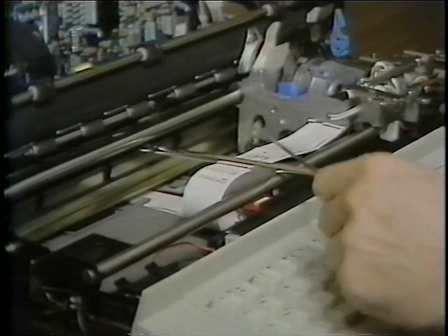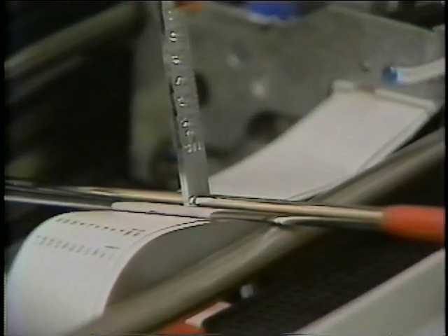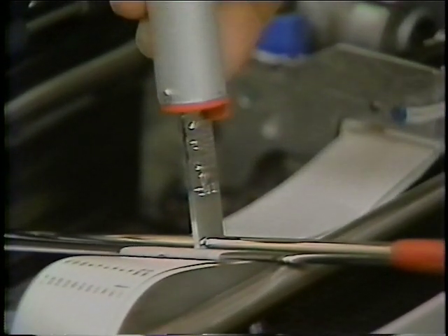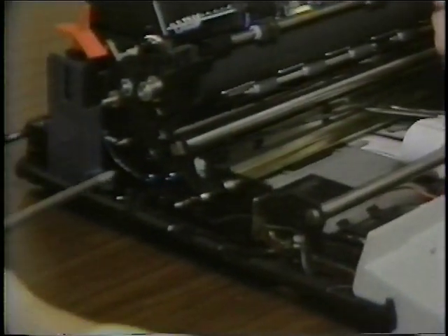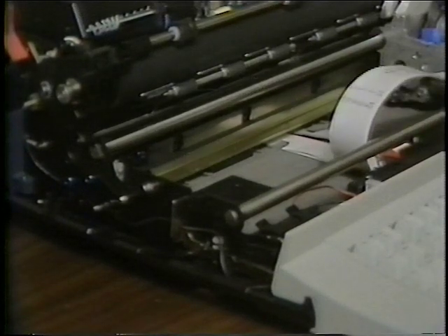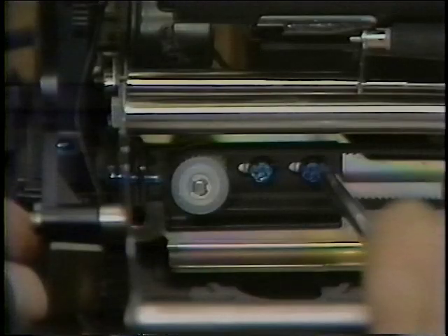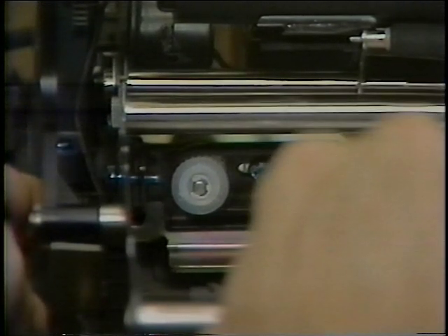Then slide the T-bender over the top of the transport belt at its center and rest the T-bender on the front shaft as shown. Place the spring scale on the T-bender 30 millimeters from the center of the front shaft. Apply 5 3/4 to 6 1/4 pounds of pressure on the T-bender at a 90-degree angle. Then turn the adjusting screw in or out so the bottom of the T-bender just touches the bottom transport belt. Finally, tighten the idler pulley bracket. This completes the transport belt adjustment.